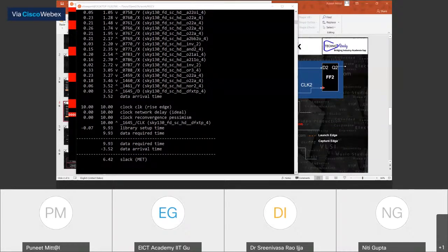So, last, setup and hold. Why is hold independent of the clock period, unlike setup time? Harish, again, it's independent of the clock period. It's basically in a single cycle. I explained to you that we are not going to take the clock period into consideration. But if we talk about multi-cycle, then maybe you have to take it.